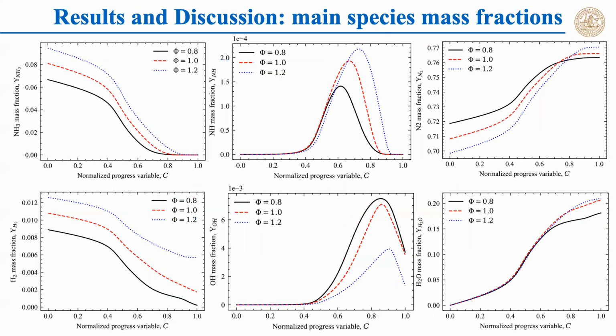This 6th figure shows the mass fraction of the fuel, important intermediate species, and main products of the ammonia-hydrogen combustion. Ammonia generates NH and finally produces nitrogen. Hydrogen generates OH and finally produces water vapor. All of the equivalence ratios are plotted, including fuel-lean, stoichiometric mixture, and fuel-rich conditions. It seems that in all conditions, the species mass fraction has a 1-to-1 correspondence to the optimal progress variable. It also evolves smoothly, which means that the current progress variable is good.